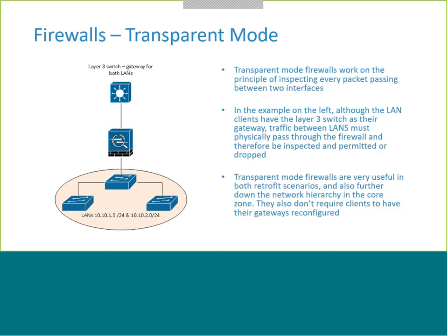Okay. So in terms of retrofit, you could add a firewall. Do they have learning modes that would make it easier? Some do, yes. I know in the Hirschmann world they make it quite easy for you, or at least easier. And they do have a learning mode. It's a transparent device when you put it in learning mode. It passes all traffic through, doesn't filter anything, but while it's doing that, it's inspecting all the connections. And after a number of hours, a number of days, or however long it may be, you've essentially got a big list of rules there, almost a baseline of the traffic that's passing through it.